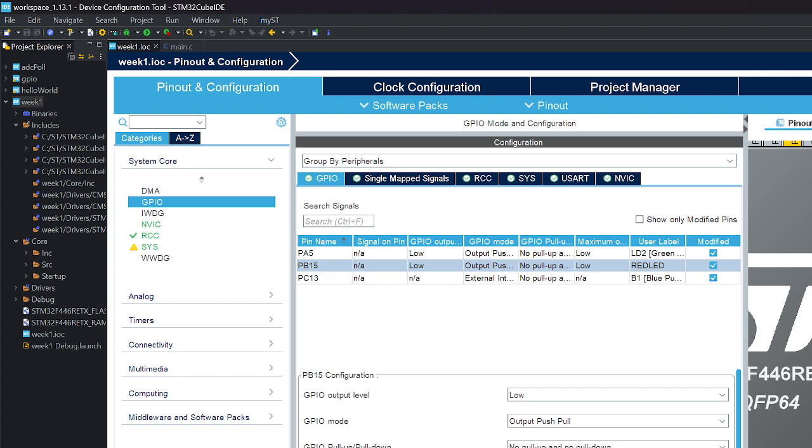Yep. So with the GPIO output level, is that effectively changing whether it's active high or active low? Yeah, this output level, when I go and initialize it and it first becomes an output, it sets the levels. It fires up from default with everything as an input, and then it will put it as an output. So when you first become an output, instead of high impedance when you're booting up and run that GPIO init, do you want the level to start high or start low?